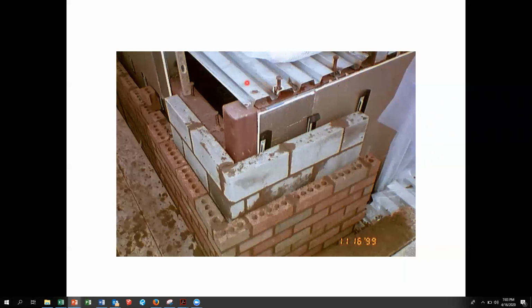There's your corrugated metal decking. These are called stud shear connectors. And if this thing is concreted in, then this gives it more load carrying capability. It looks like a bolt that's been welded to the top flange of the beam. What's this right here? That'd be a good test question. And you laid them out in surveying in lab. That's your 6x6 column. Yep. That's your 6x6 column.